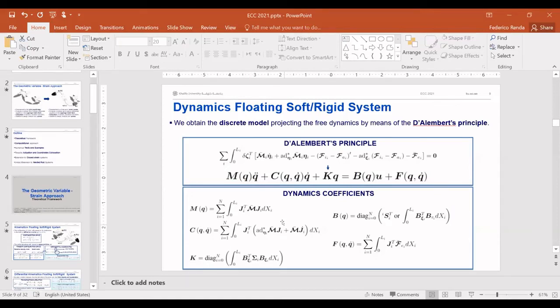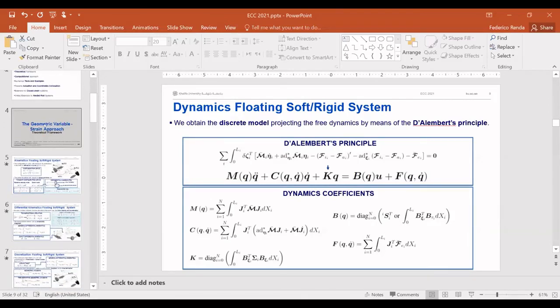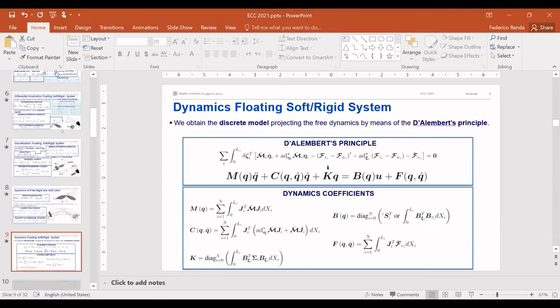Yes, so we are considering here rigid cross-sections. So it's a constitutive, if you want, model, that the cross-sections are rigid and they don't change. Yeah, exactly. That's also, as we did in 2007, the paper you may know. But I think that if you want to extend it to sections which are not rigid, you need to go to a Hamiltonian, because the Lagrangian would fail. That's my expectation. Thank you.